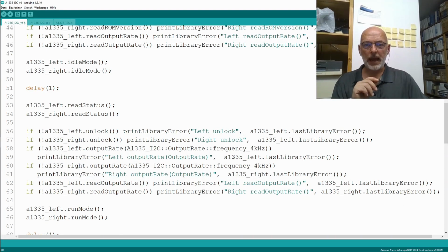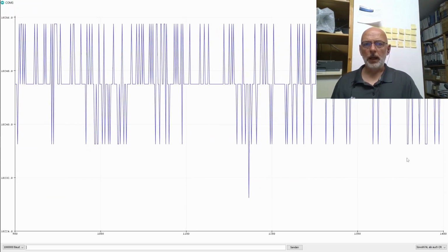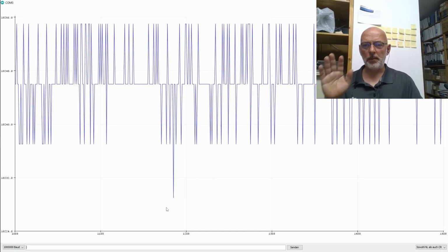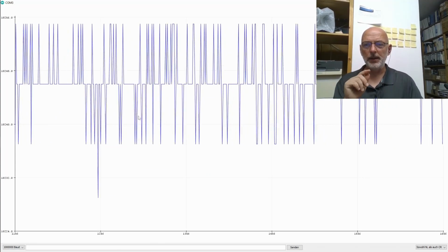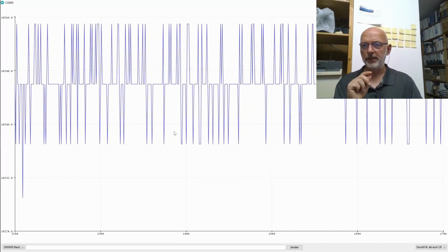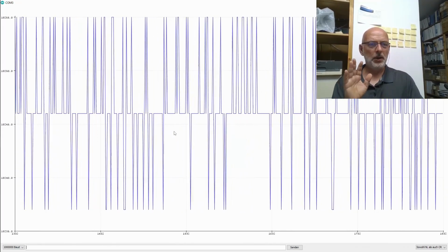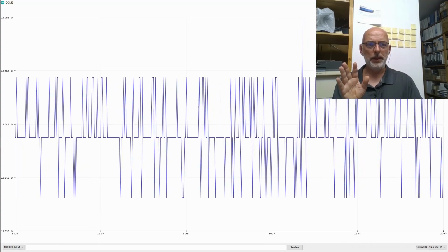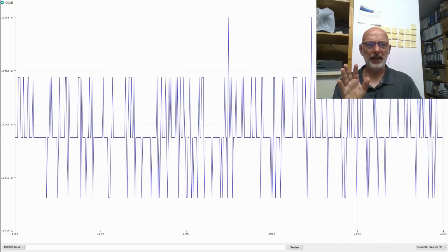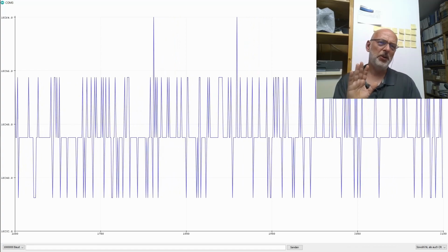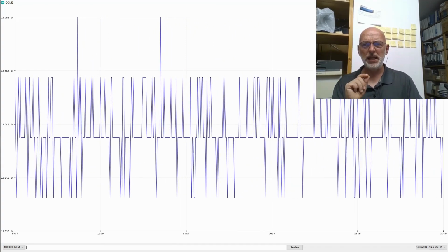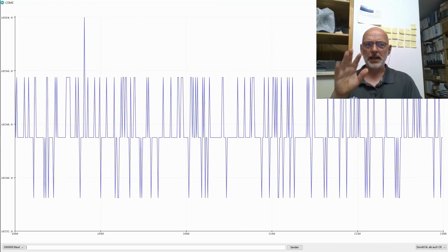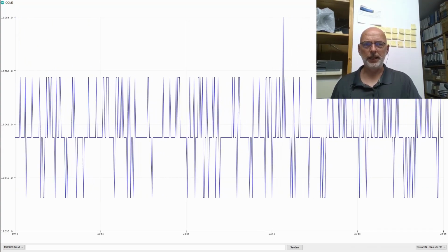We're down at 4 kilohertz, so averaging over 8 samples now. And as you can see, our plus minus 2 least significant bit spikes are really just few and far in between. I'm almost willing to call that a noise of 3 LSB. Yeah, let me take a hard copy and watch it a little bit longer.